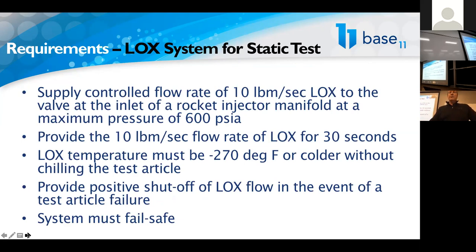We want to provide cold liquid oxygen to your test article without chilling your test article. Maybe you have some elastomeric O-rings, maybe you have, what do we call it? What kind of chamber did you guys have? An ablative chamber that you don't want to freeze or saturate with liquid oxygen.